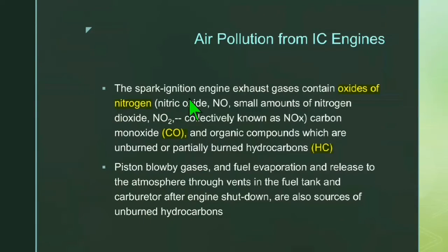The spark ignition engine exhaust gases contain oxides of nitrogen, that means nitric oxide, NO, and small amounts of nitrogen dioxide, NO2, collectively known as NOx, carbon monoxide, CO, and organic compounds which are unburnt or partially burnt hydrocarbons, HC.